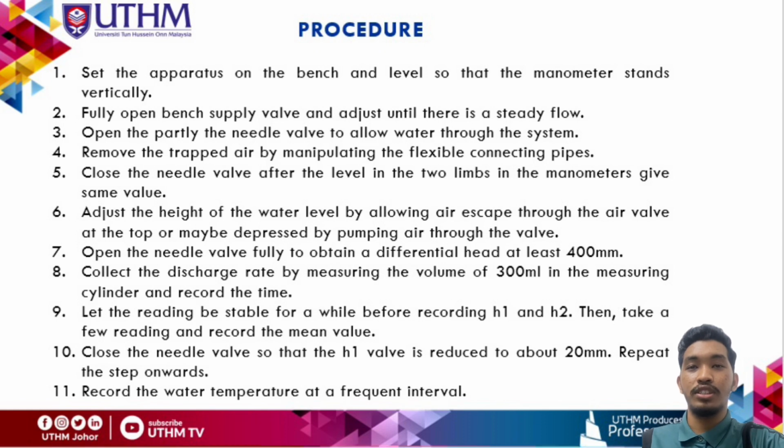Okay, this is the procedure of the project. First, set the apparatus on the bench and level it so that the manometer stands vertically. Second, fully open the bench supply valve and adjust until there is a steady flow. Third, partly open the needle valve to allow water through the system.